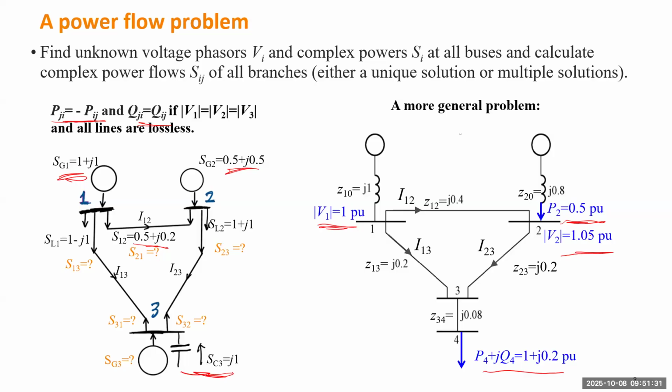This is pretty much a generator. If it's a generator bus, we can control the active power. We'll talk about how to control the active power, or dispatch among multiple generators, in the next session, Session 7, the optimal dispatch section. And for each generator, I can decide what voltage I need to operate at.